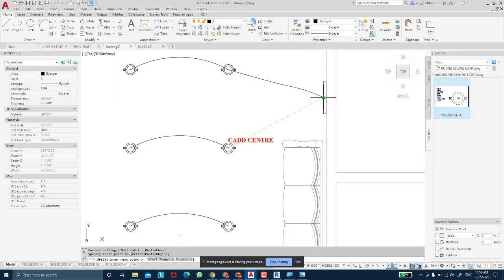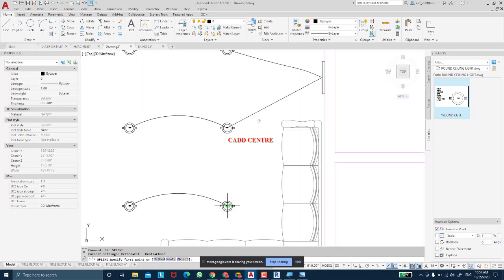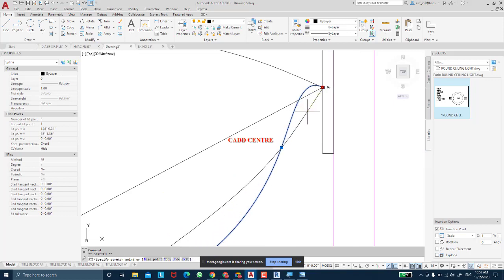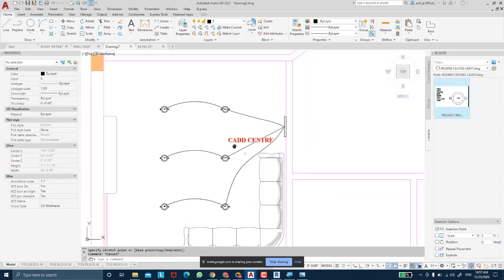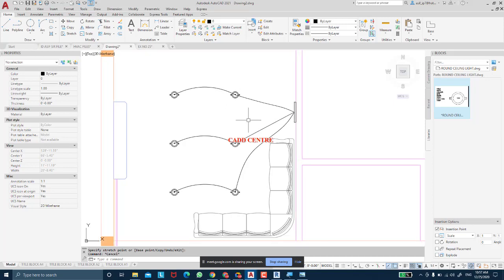These two lights would again be powered through that switchboard. Now why did I do this? It means I will have only 3 switches for 6 lights. When I switch on one switch, these 2 lights would be switched on because they are being looped. Okay, can you see? Looped up.